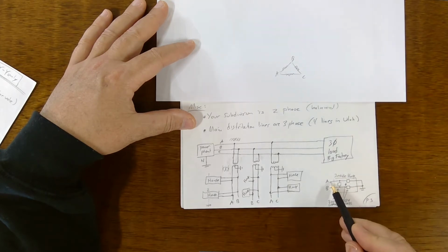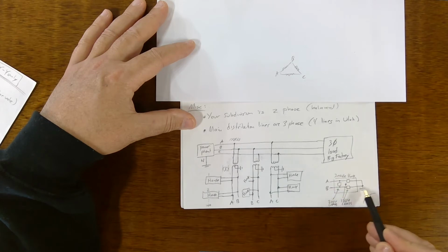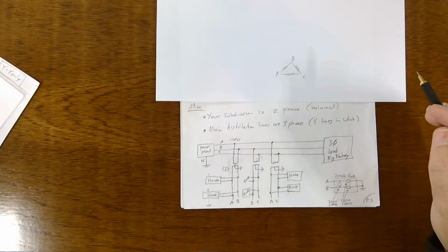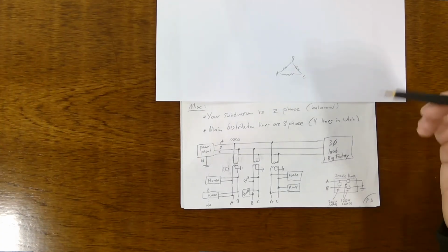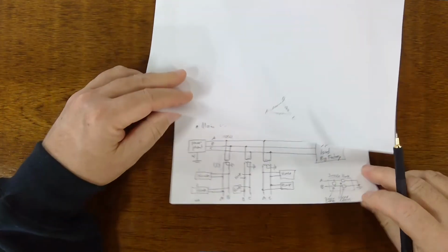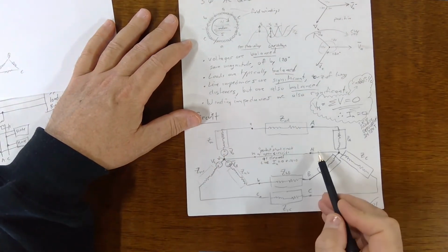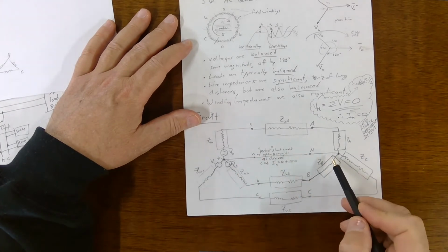Some of your loads in your house are pulling off of the A phase to neutral, and some are pulling off B phase to neutral, and you want to have approximately the same number on each side to keep your house in balance. But over 100 houses, this is all going to balance out on average. Any unbalanced loads would go back through the neutral. If these three weren't ideally balanced, the remainder would go through the neutral.